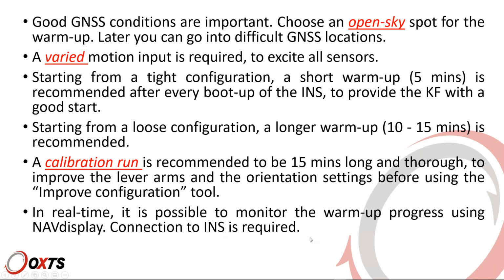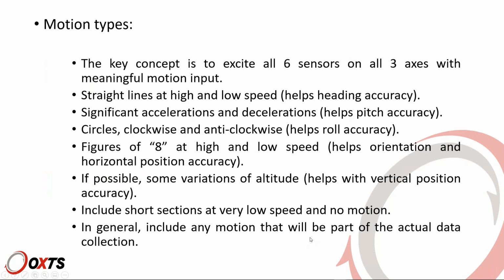In real time, if you want, you can monitor the warm-up progress using NavDisplay. There are templates that we provide that can tell you your position accuracy, velocity, and orientation accuracy, and you can check how that is improving as you progress in your warm-up.